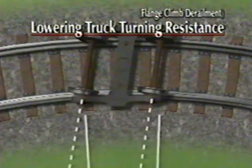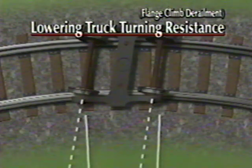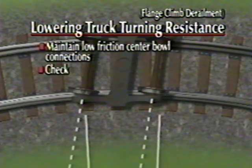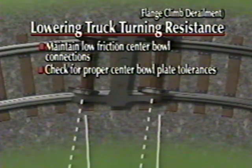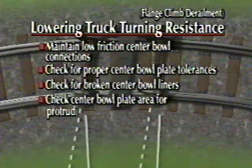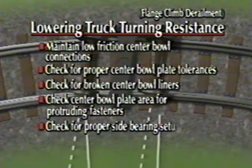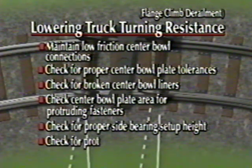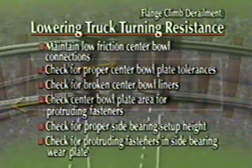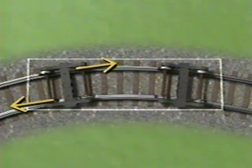Let's review the efforts that will reduce truck turning resistance, like keeping center bowl friction low, checking center bowls and center plates for proper tolerances, checking for broken center bowl liners, inspecting the center bowl center plate area for protruding fasteners, checking for proper side bearing setup height, and inspecting the side bearing wear plate for protruding fasteners.